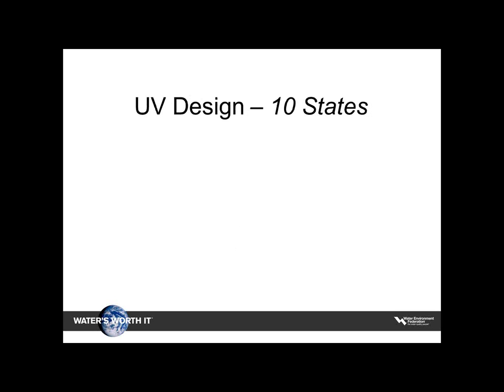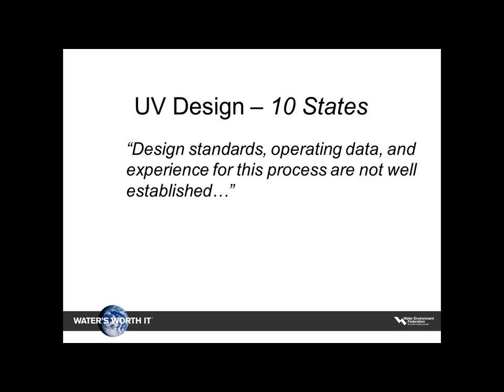Then the classic fallback, which is amazing how many states, more than 10, I can tell you that, use Ten State Standards. And the best part is the first line in Ten State Standards about UV disinfection is this: design standard, operational data, and experience are not well established.